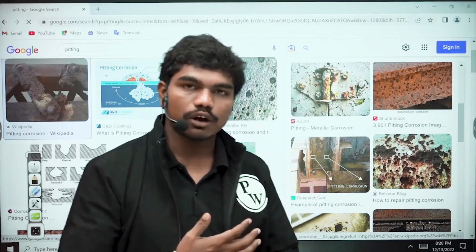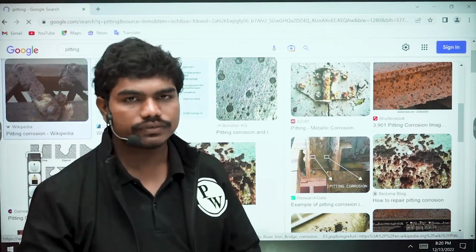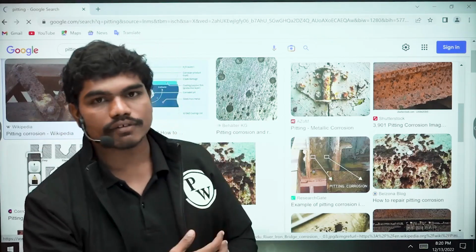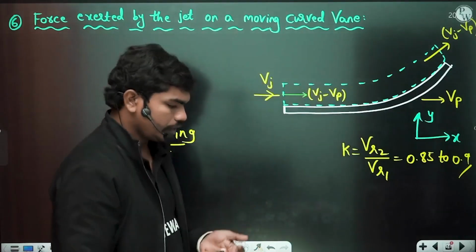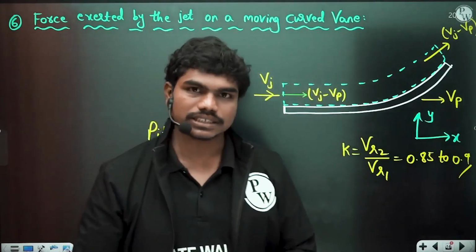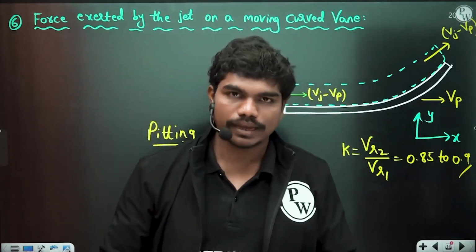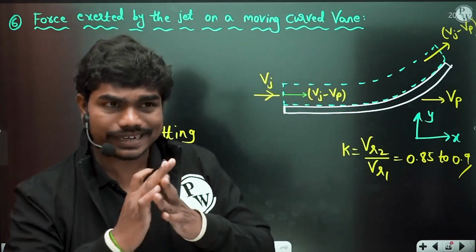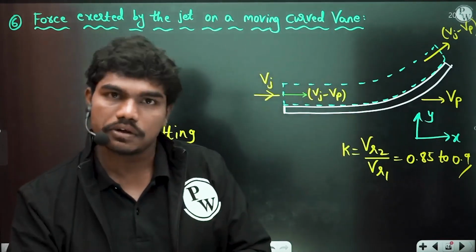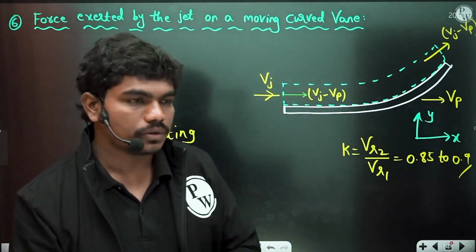So the fluid cannot slide smoothly, and the efficiencies of the machines will definitely fall, because outlet velocities will decrease. Whenever the outlet velocities decrease, definitely the momentum change will decrease. So the force acting by the fluid on the rotors or on the blades will decrease. Whenever it is decreasing, your immediate job is to maintain that, to handle the equipment.